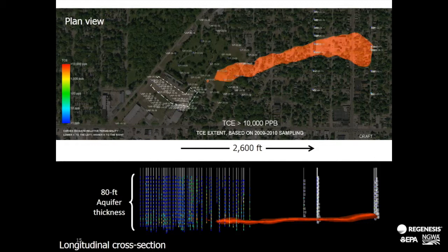And the upper part of this formation is extremely high hydraulic conductivity. There's some zones in this that are near full centimeter per second hydraulic conductivity. There's an underlying basal clay, a lacustrine clay. But what we found was that about a quarter mile off site we're finding high concentrations, but they're in the lower K zone. It's not clay, but it's silty sand and fine sands where we're finding the highest concentration immediately adjacent to very high K transport channels. Up above, we don't have that lower K material.